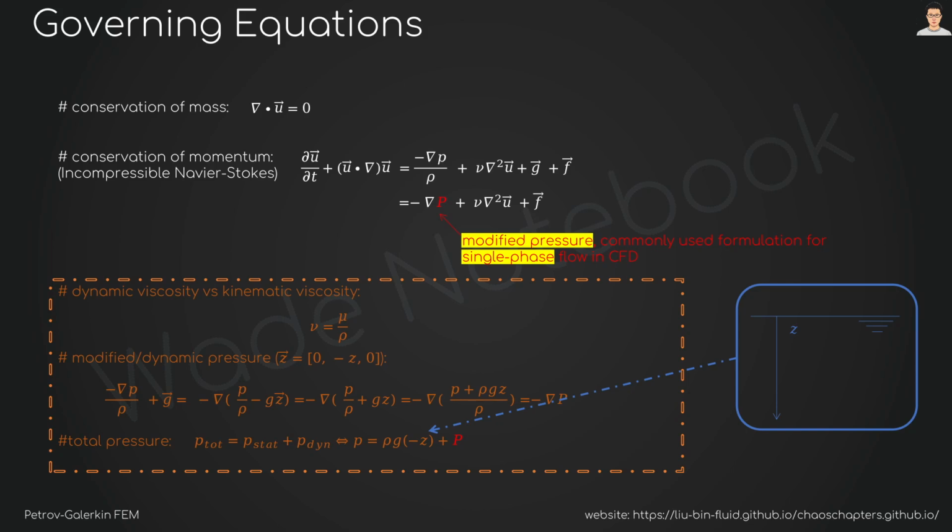For instance, water is one of the most common fluids, which has a density of 1,000 kilograms per cubic meter. If we multiply every term in the Navier-Stokes equation by 1,000 in the case of water, the difference of magnitude between the fluid density, which is 1,000, and the minimum number in the computational field, which is usually 0.001, the common convergence error in finite element formulation, can be as large as 10 to the power of 6. This huge difference in the order of magnitude of the numerical solution can tremendously increase the condition number of system matrices and possibly lead to the divergence of transient simulation.